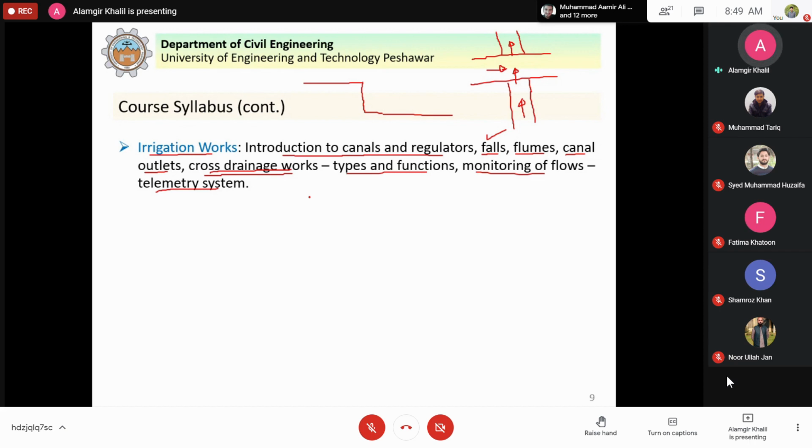Now to measure the discharge this way every day is very difficult, and if we have so many points along the stream or river, what we do instead is develop a rating curve that you studied in hydrology. That is the discharge versus the depth of water at a gauge section.